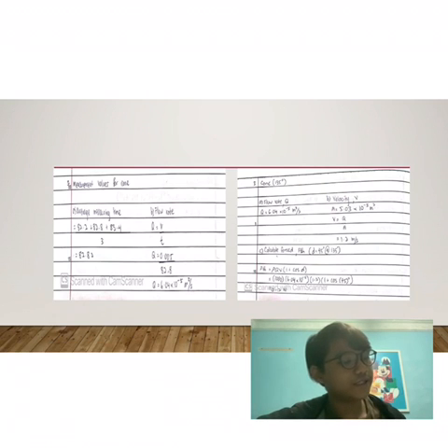And for the flow rate, 0.005 divided by 82.8, and the answer we get is 6.04 times 10 power of -5. And the result for the cone is: A equals 5.03 times 10 power of -5 square meters, and the flow rate is 6.04 times 10 power of -5 cubic meters per second. So we get the answer for velocity is 1.2 meters per second.